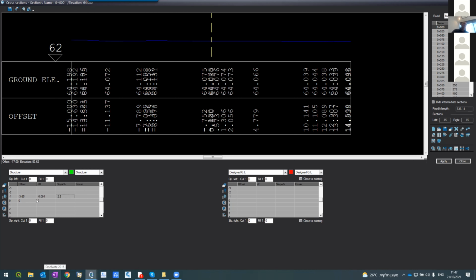Slope of -2.5, fine. How do I enter? Very important. We put 0, enter, 0, enter. Again, from the center outside. And then -3.65, very important to press the enter. I don't enter anything in the DH, I go to the slope and then enter minus 2.5 and press enter. The DH will be calculated automatically.